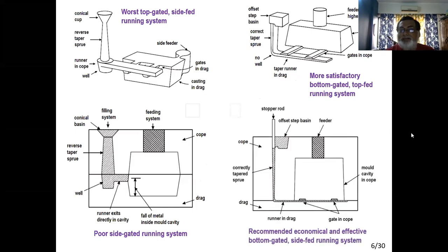Okay, this is a version of the bottom pouring system where the channels are even narrower. Instead of this one, here is a very narrow sprue. It could be rectangular, it could be circular as well. And the runner is very slim, very thin, and the gates are also of small section. As a result, the liquid metal requirement in the gating system is very small.